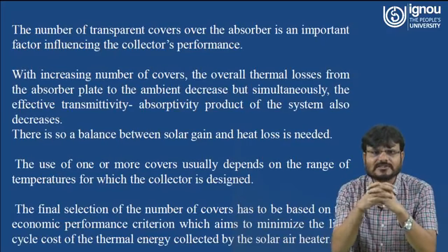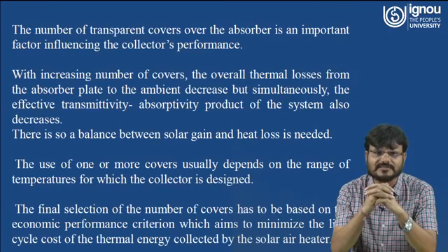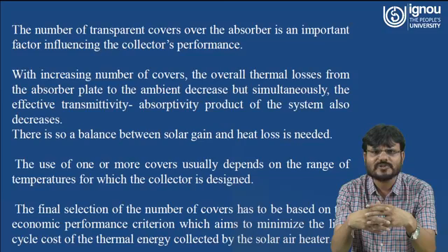Here you can notice the number of transparent covers over the absorber is an important factor influencing the collector performance. With an increasing number of covers, the overall thermal losses from the absorber plate to ambient decrease. But simultaneously what happens? The effective transmittivity-absorptivity product of the system also decreases. So what do you have to do?